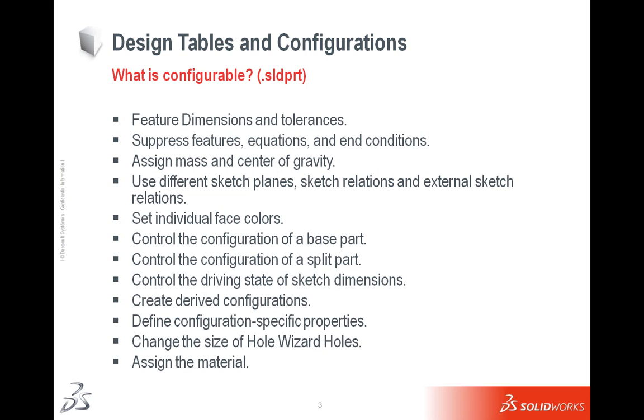When I say configurable, these are the things that can vary between one configuration and another. I can change the center of gravity that I've assigned. I can change individual face colors. I can change sketch relations. Okay, there's a whole bunch of things, hole wizard sizes, materials, and so on, are all configurable within part files.